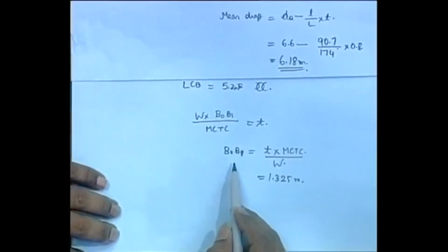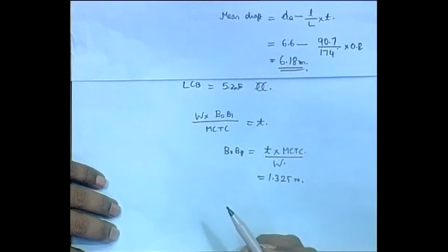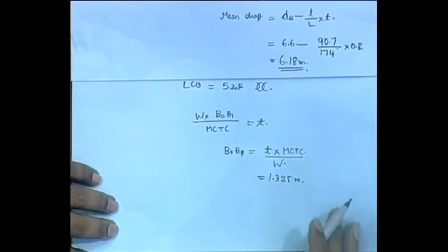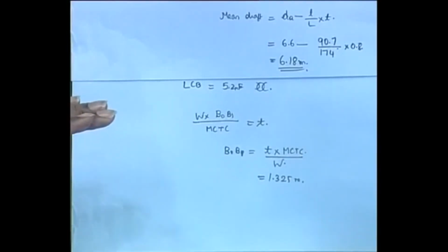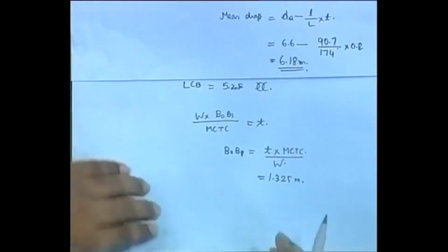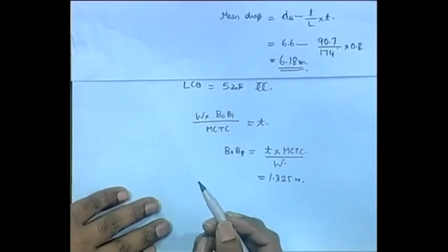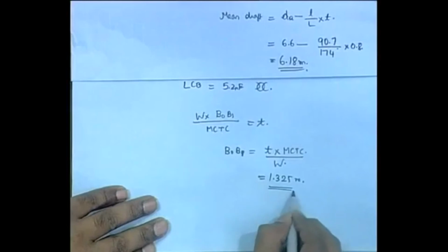So, we say that the distance through which B has shifted from its initial position, LCB, we can assume this is a faulty design, such that because of the design, LCB and LCG didn't come at the same place, or maybe you added more load than the design itself says. Whatever happened, LCG didn't become equal to LCB, as a result of which B shifted to reach G, and so it moved this much distance.